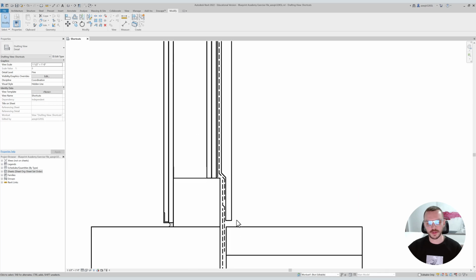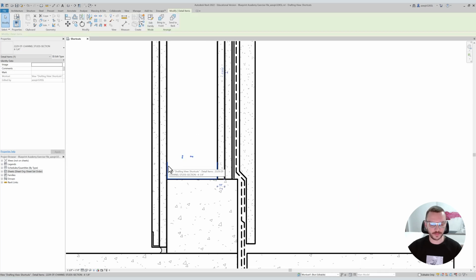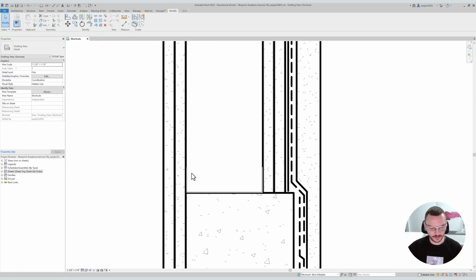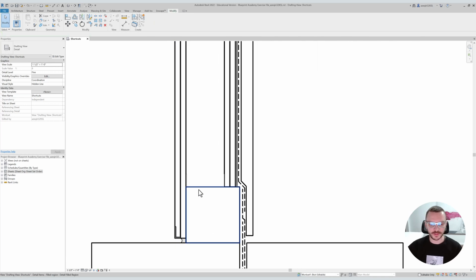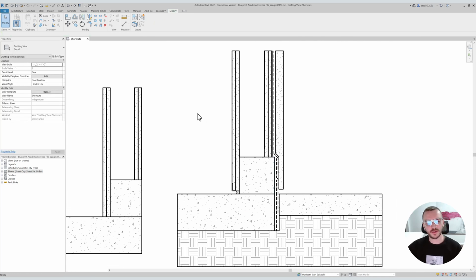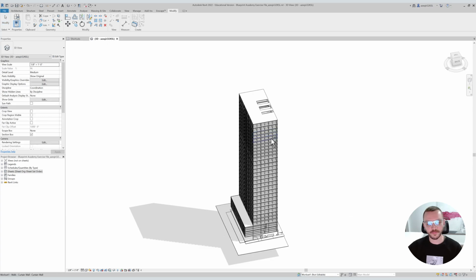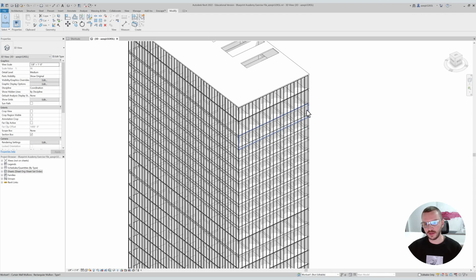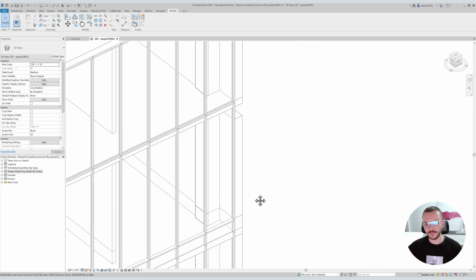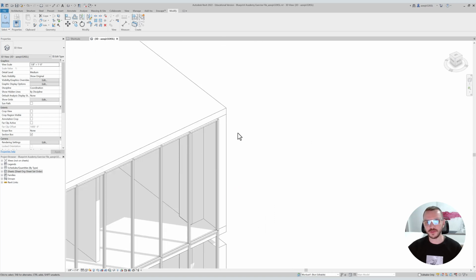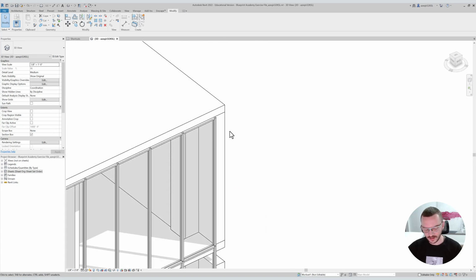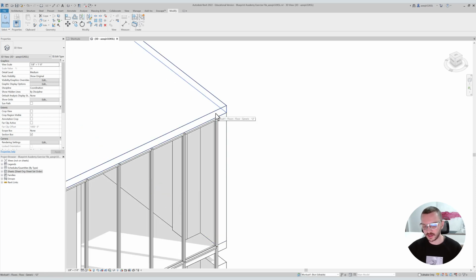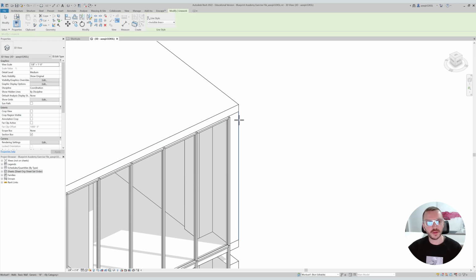Alright. Something like this, right? So, LW. It doesn't work for detailed components, but it doesn't matter if we're in a section view, a 3D view, plan, whatever. As long as you're selecting a model element, you can hit LW, and for example, we have invisible lines selected, and then you can hide some lines.